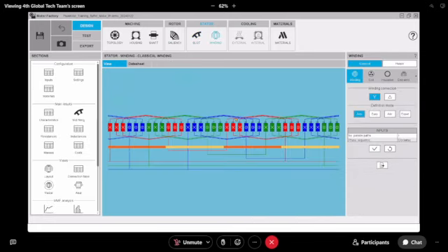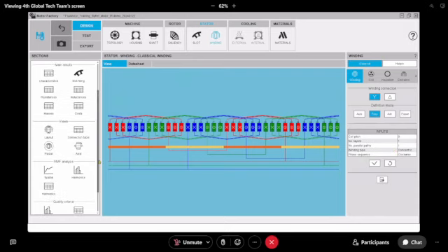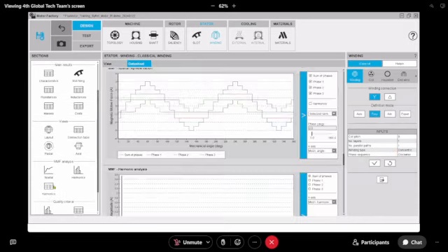Then the winding, which in Flux Motor has a really helpful tool depending on the number of poles and the number of slots. Flux Motor will be able to propose different configurations. So it's up to you to test the different configurations and then see the spatial MMF, what we were talking about when talking about Ampere's law.